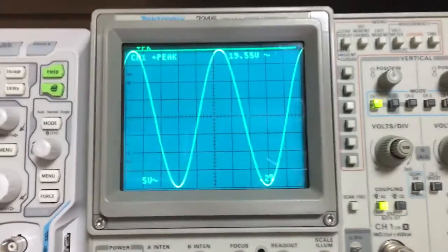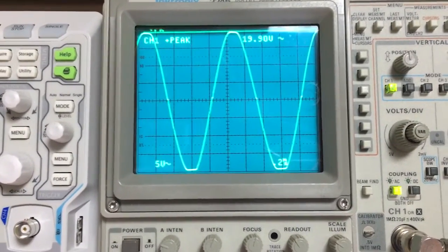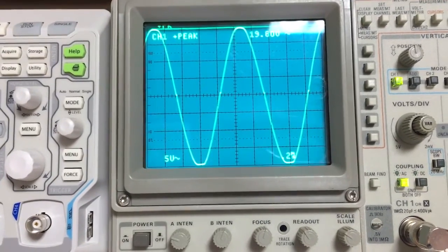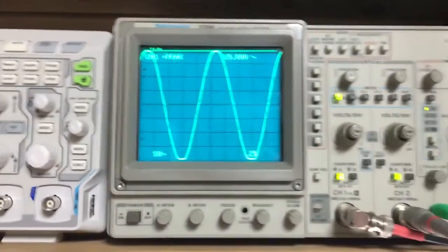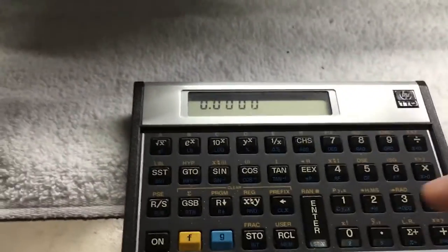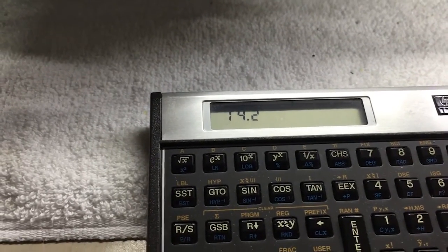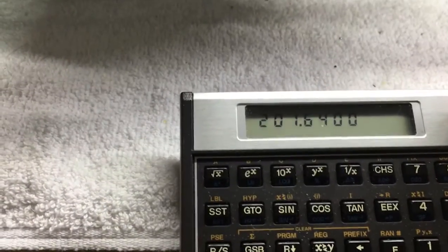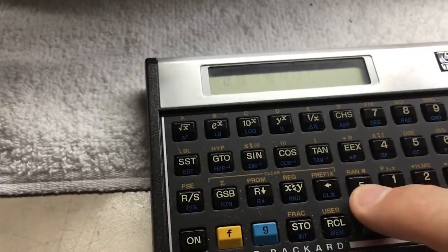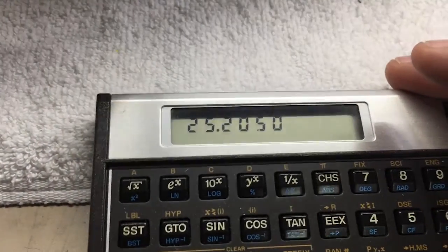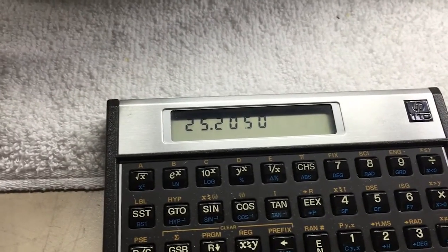So let's push it here until it just starts to clip, just right before clipping. Right about there, I think we're at 19.85 volts or so, okay? And we can look up here and see that that's 14.20 volts RMS, right? Come down here to this thing. Since we know the RMS voltage of 14.2, we store that, we're going to square it, so we put in 2 square, then we get back 201.64, right? And then we store that and divide by 8 ohms, and bam, look at that, 25.20 watts output this thing is putting out right when it's starting to clip.